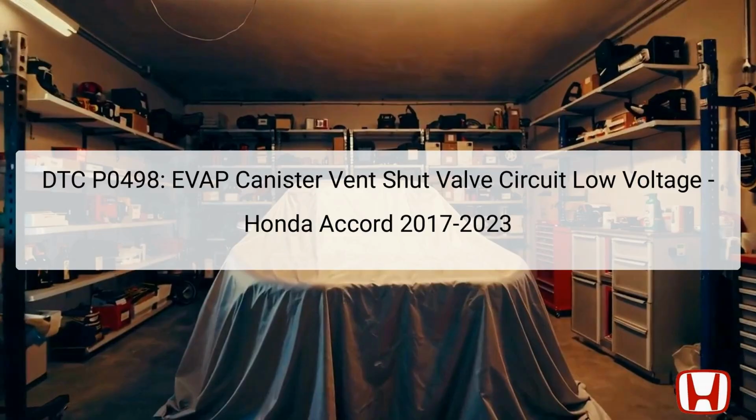DTC P0498 indicates a significant issue with the EVAP canister vent shut valve circuit due to low voltage. The EVAP, evaporative emission control system, is crucial for controlling fuel vapors and preventing their release into the atmosphere. The canister vent shut valve prevents vapors from escaping the EVAP system during certain engine conditions.